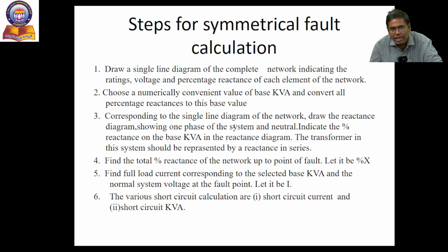Steps for symmetrical fault calculation: how to calculate the fault current or short circuit current. First, draw the single line diagram. There are different steps for calculation of short circuit current and short circuit kVA. If these steps are followed, we can solve the problems very easily. First, for the given power system, draw the single line diagram of the complete network, indicating the ratings, voltage and percentage reactance of each element on the network.